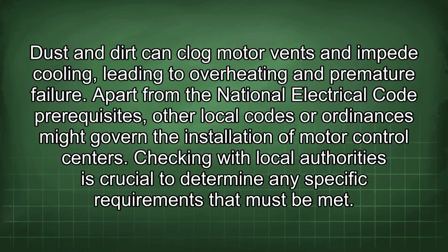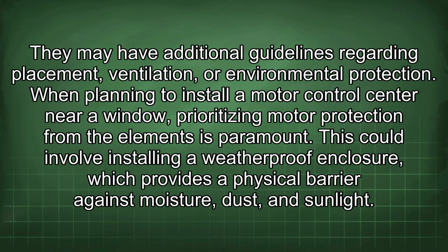Apart from the National Electrical Code prerequisites, other local codes or ordinances might govern the installation of motor control centers. Checking with local authorities is crucial to determine any specific requirements that must be met. They may have additional guidelines regarding placement, ventilation, or environmental protection.